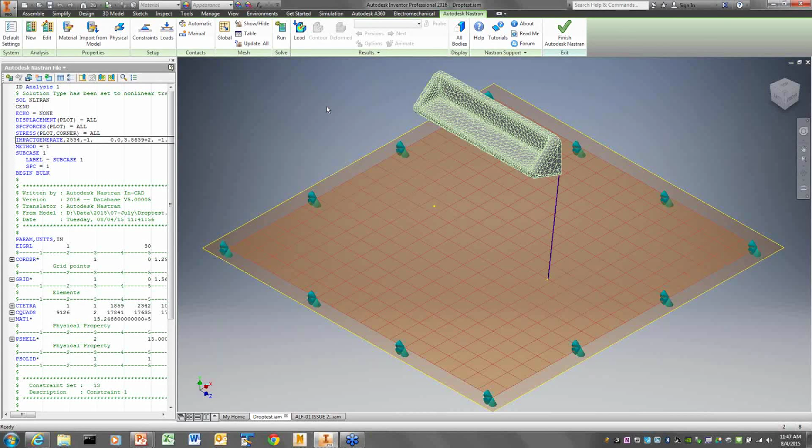One thing you'll always find is if I've got a cube and I drop it on the corner and I don't include any material plasticity, you're going to end up with really, really high stresses on that corner that just aren't going to look right. But anyone knows that if you drop a steel cube on a carpeted floor, you're still going to dent the corner of the cube. So at that point, you really need some kind of plasticity. And again, look at what kind of plasticity you get. Because on drop testing, you almost always will have some degree of deformation at the impact point, just because it's an initial point. The whole weight, the whole velocity, the whole energy is concentrated at a single point.